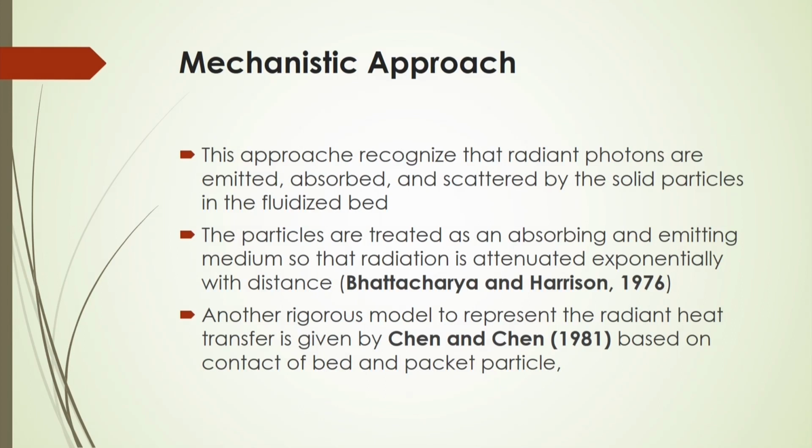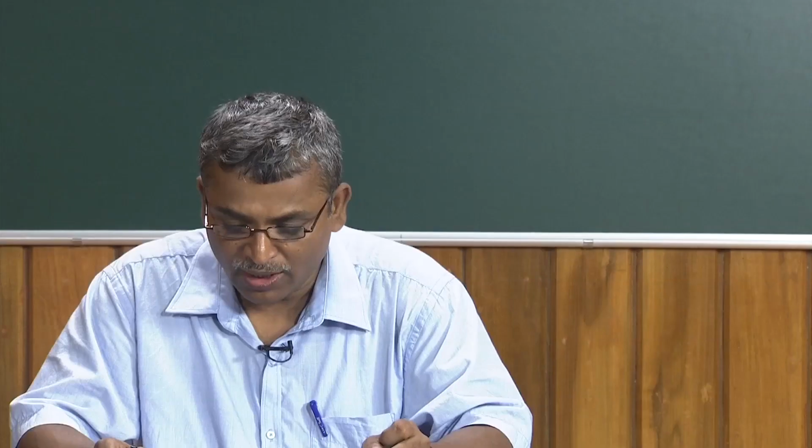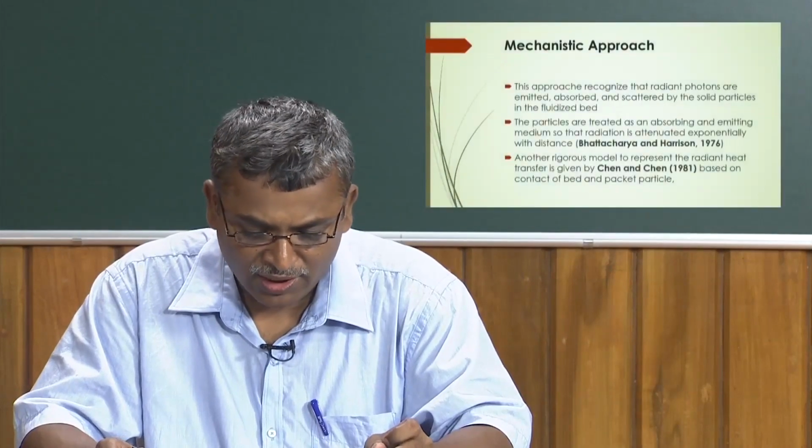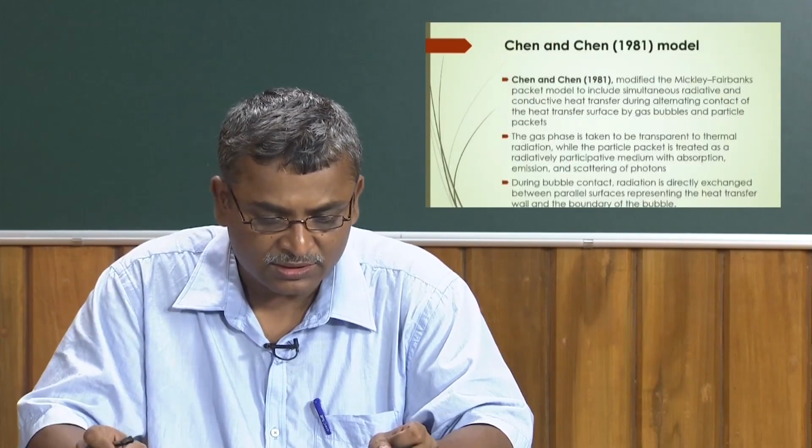The particles are treated as an absorbing or emitting medium, so that the radiation is attenuated exponentially with the distance. Another rigorous model developed to represent the radiant heat transfer is given by Chen and Chen 1981, which is based on the contact of bed and packet particles.